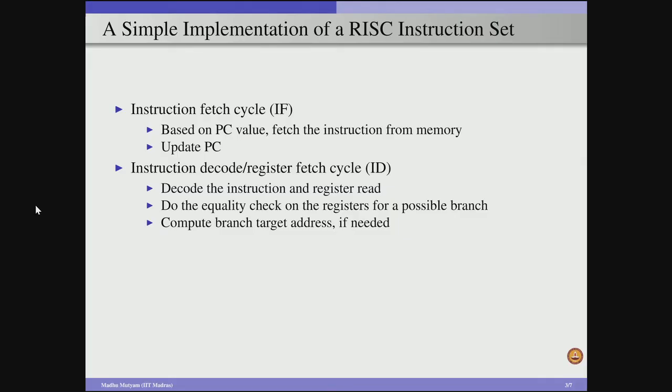So, once the instruction is stored in the instruction register, now we need to see what type of instruction this is, the instruction we just fetched, because we know that when we fetch an instruction from the instruction cache, it consists of a stream of bits. Unless we decode this stream of bits, we cannot say what the role of this particular instruction is, whether it is going to perform a read operation, a write operation, an ALU operation or something else.